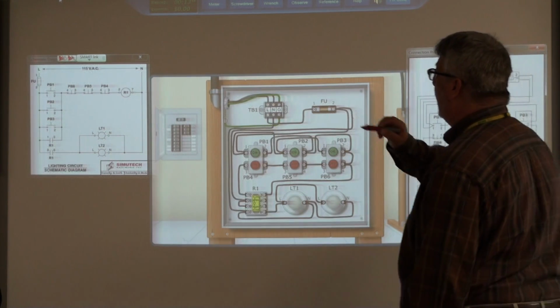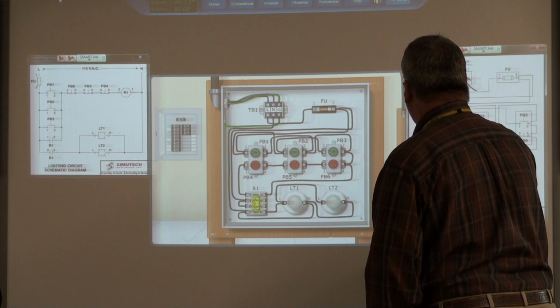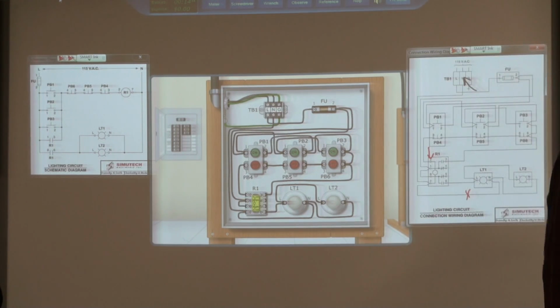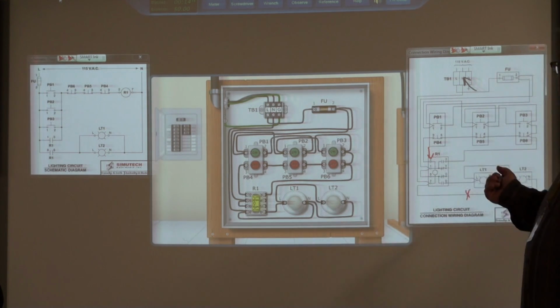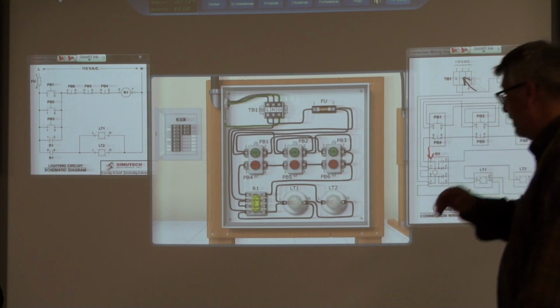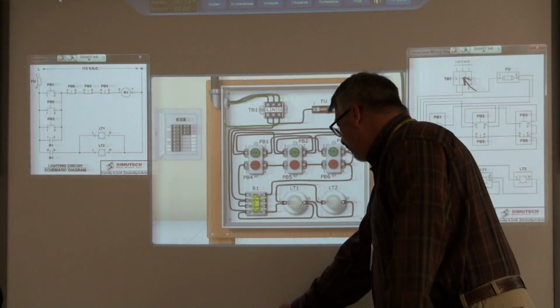Now, looking back at this over here, what am I going to measure on pin 2 of my relay? 115. We're still engaging the relay coil. Nothing about this neutral opening up has stopped that, so we're going to read 115 volts there.